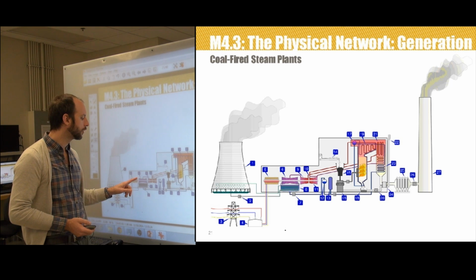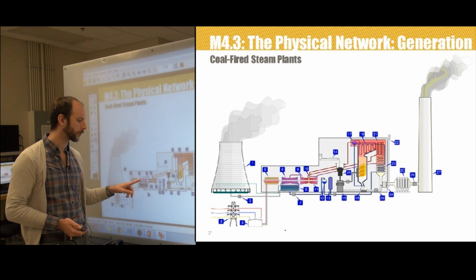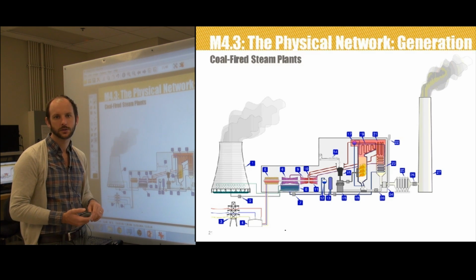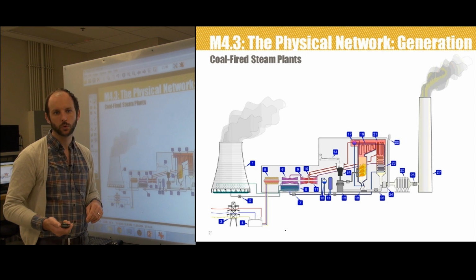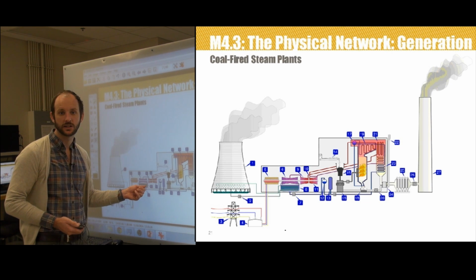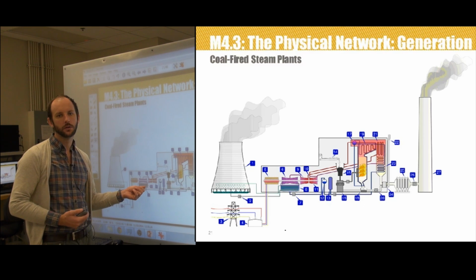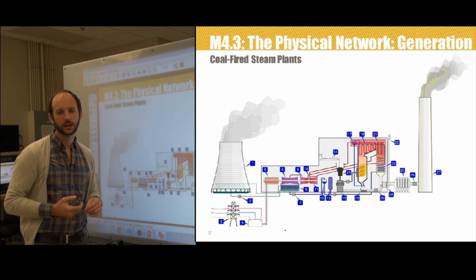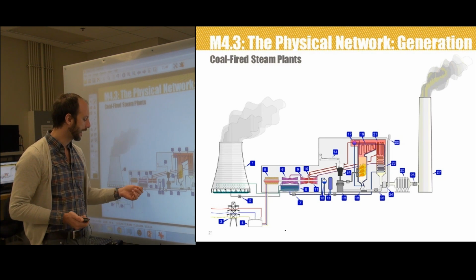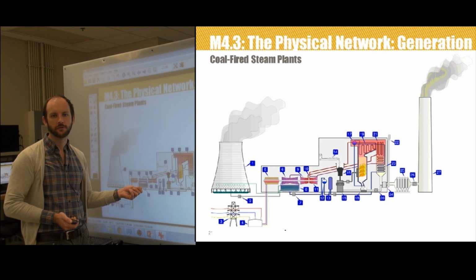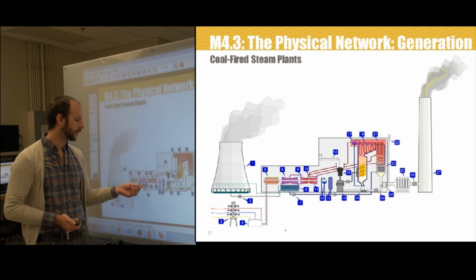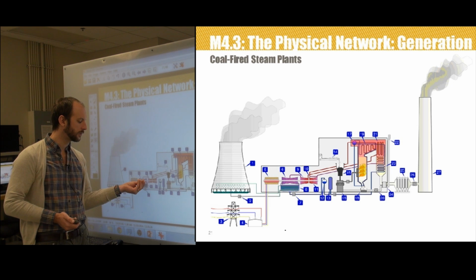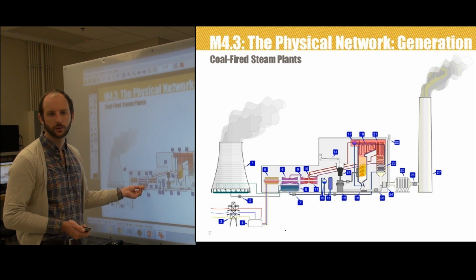So we've now basically used up all the useful thermal energy and pressure in this steam. It's a little bit above boiling point. It's then brought into thermal contact with cold water, which is being pumped in from the cooling tower, inside of number 8, the condenser. And here, the boiling hot steam coming from the low pressure turbine is condensed rapidly back into water. That creates the side effect of creating near vacuum-like conditions inside of this condenser. And so actually the condensation causes a natural process by which the steam is sucked into the condenser through vacuum action.